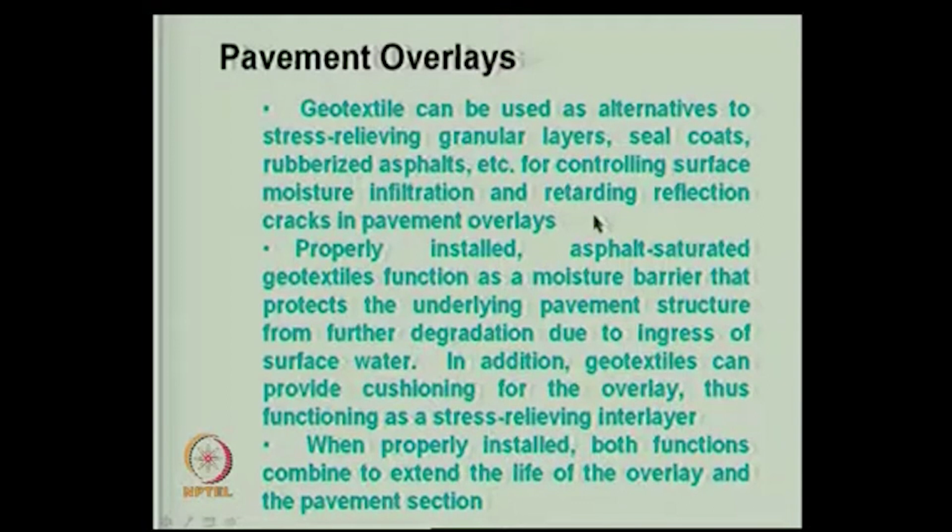In fact, I know that we have the Yelahanka airfield pavement, which was being used for aero shows. Even now it is being used, and they wanted to rehab it. When the flights come and take off, they introduce a lot of stresses into the pavement, and the stresses at the top layer are very high, both while landing and taking off.